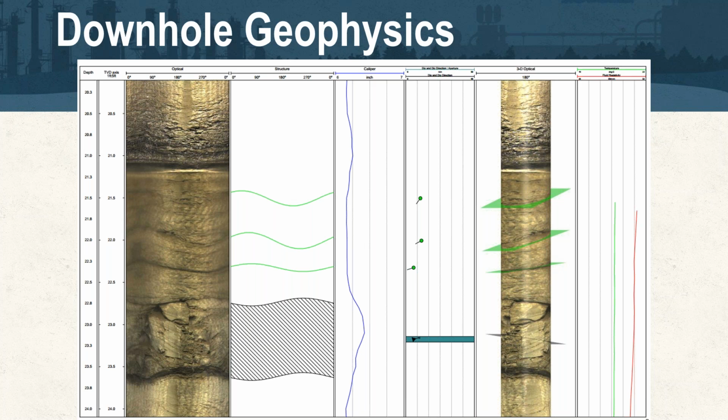In other cases, doing the rock cores, doing the discrete sampling up front, you may break up your borehole installation into a couple phases. You may, say, put in 3, 4, 5 boreholes here, do phase 1 of an RDC, analyze the data you've got back, and decide, do I need to add some additional resolution in this part of the site, in this part of the plume? So breaking up the phases can help.